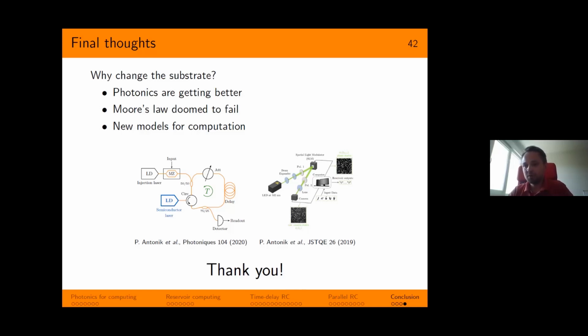If, however, we want to make things faster or more efficient, or we switch to free space or coherent light, there we need to stabilize our light path because coherent light interacts. And if we have the delay loop that comes back with a phase difference that destroys all the signal, it's a problem. So yes, coherent light systems need to be stabilized. You need to stabilize the cavity with a piezoelectric or some PID or something like that.